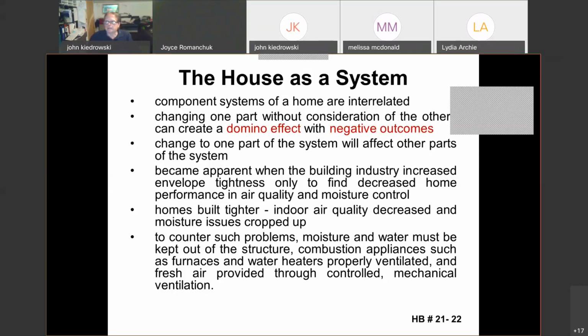Drawing fresh air in through my heating system, it's tempered, and also it's going to be heated or capturing the heat coming back from the space in exchange in my heat recovery ventilator, we'll call it a box. So my HRV's in my basement, not too far away from my forced air furnace.